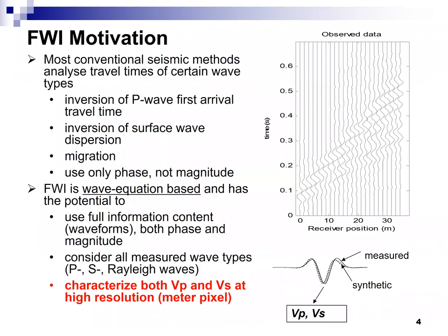So the horizontal axis here is the receiver position. That is a 2D problem. The vertical axis is time domain. The signal that propagates through the void or soft material takes more time to travel and will show up as a later point in the measured data. So if we use only first arrival signal, like refraction tomography, we miss the entire information of the void. We need the later point in the measured data to identify the void.